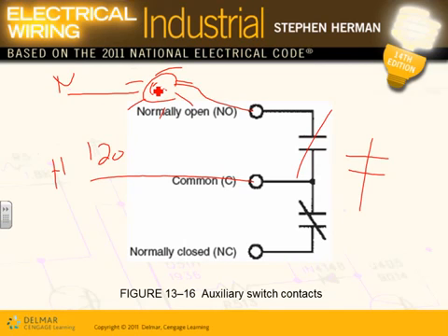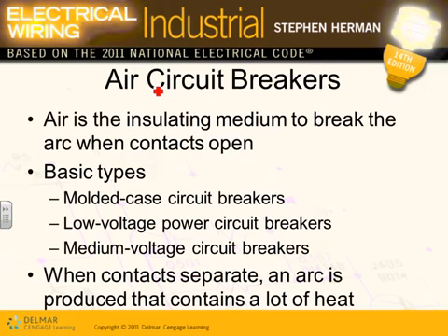Any comments, gentlemen, about auxiliary contacts or switches and shunt trip? Very, very important. This big boy has tons of auxiliary contacts and shunt trips that you can remotely trip. You can push your iPhone and turn this on and off from your iPhone. That's through the auxiliary contacts and so forth. So it's a big deal with bigger breakers. Okay, air circuit breakers.